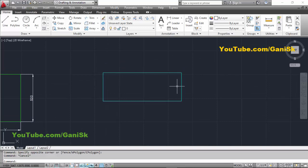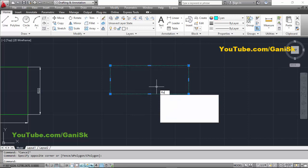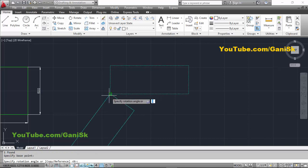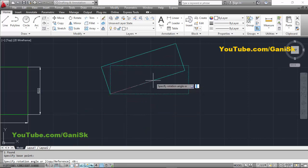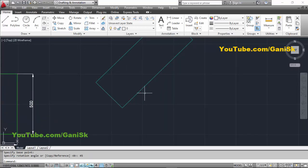Before checking the dimension, we are going to rotate it. Select the rectangle, use the command RO, enter, and pick the base point here. We need to rotate with the angle 45 degrees. You can see in our command bar it's asking for the rotation angle, so type 45, then click on enter. You can see now this angle should be 45 degrees.